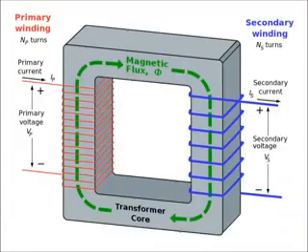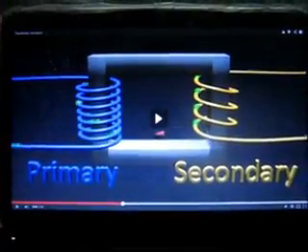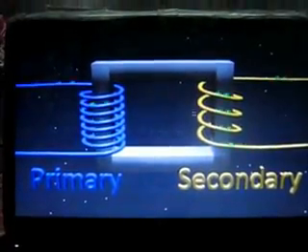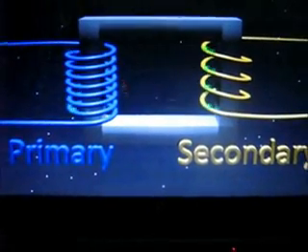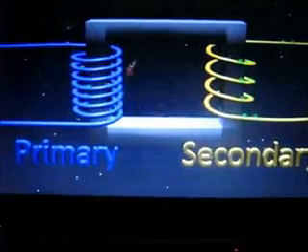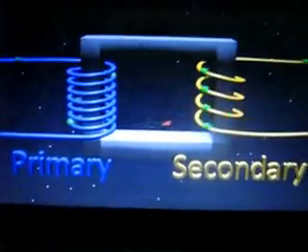Now next, coming to the transformer side, its operations and its basic construction. It is made up of ferromagnetic material. It has primary and secondary winding. As you can see, V1 produces current I1 on the primary side and generates a voltage V2 on the secondary side by the principle of induction, that is Faraday's law. The first coil produces flux, which circulates through the core and links to the second coil. As the voltage is circulating, flux is also circulating. There are certain assumptions: the windings should be lossless, the permeability of the core is infinity, and there is no leakage.